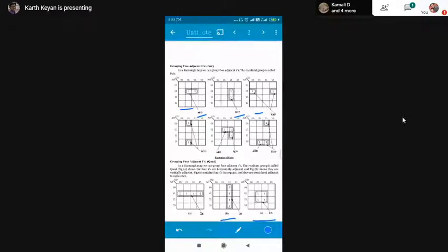Next is your third map. What happens in this? They are taking the corners. Left side you have a bar b, take it as it is. We'll go for the top: you will get c bar d bar, next is c d bar. In this, d bar is common. Okay, so likewise you can group.